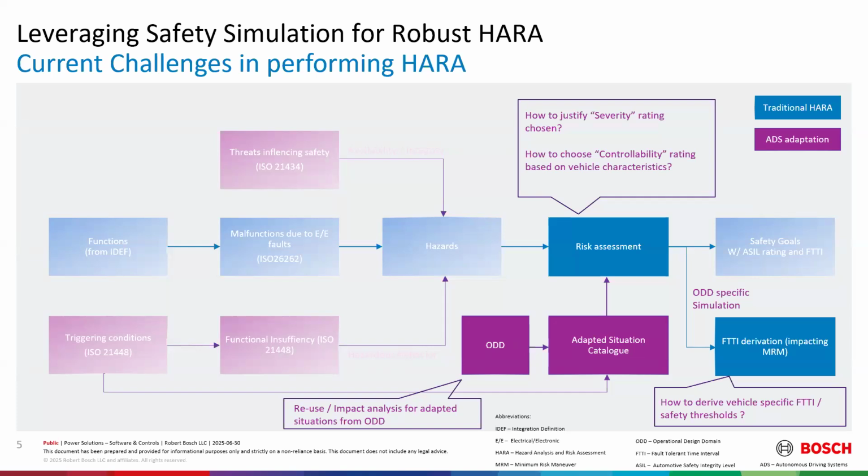Curious on the ASIL rating. When it comes to autonomy, do you see variety in ASIL or does everything fall into ASIL-D? You can still see varieties of ASIL, but again, it depends on the subsystem. A lot falls into ASIL-D when it comes to autonomous, because it directly goes to the C3 controllability rating.